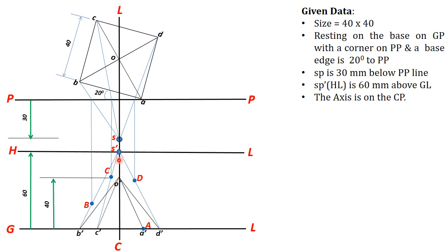Okay, we don't know what is the location here. So to find the corresponding perspective point of O, you should transfer this O to a convenient distance towards right, or you can transfer this towards left also, to a convenient distance by drawing parallel line to PP. Okay, then mark that point as O1, say it is another location of point O.